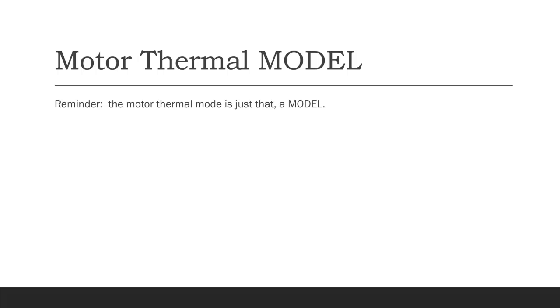Okay, I'll close that poll. And again, the motor thermal model is just that. It is a model. Without RTDs, it does not give us any real-time data, any real data as far as the temperature goes, which is what kills our insulation.